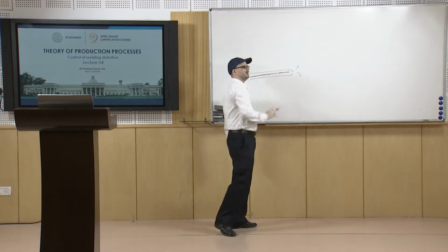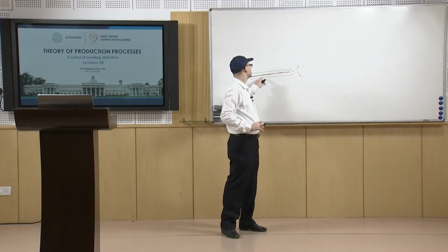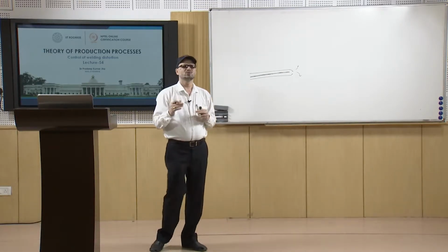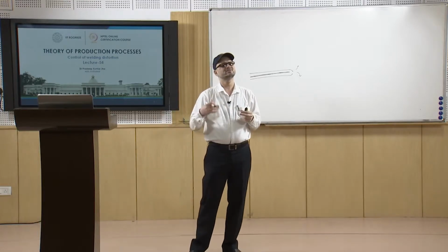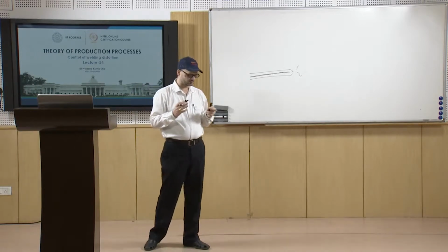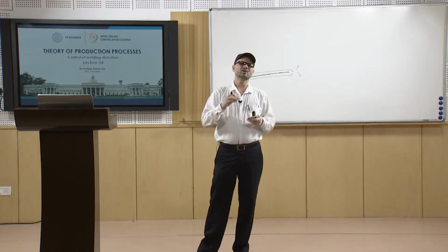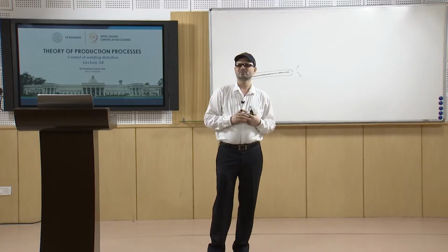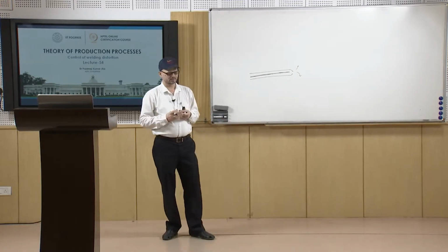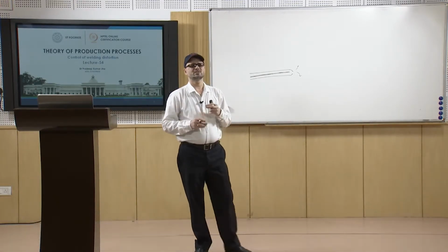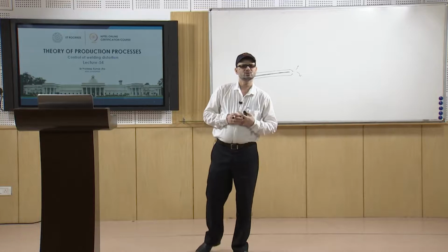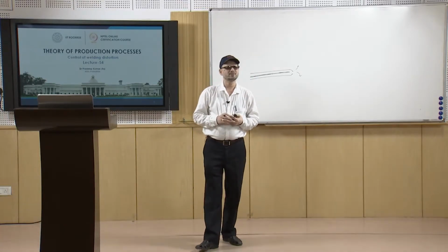So, that way, once you put the tack weld at different locations and then you are doing the welding process, that is a way to control the distortion of that type. So, that we will discuss. Narrow groove section is basically we must have a groove section which should be as narrow as possible, because that will minimize the amount of weld metal in that, and we discussed that as the amount of weld metal is more and more, it's more likely to give you the larger value of distortion. So, the narrow groove section is another important parameter.